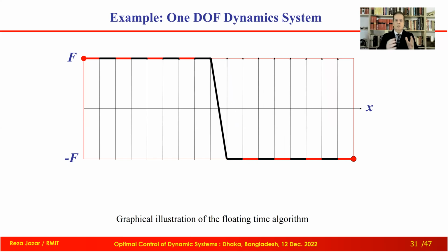Done. I don't know, maybe 20 sections. A very limited section just to show the idea. Now, if you increase the number of these increments, the solution is showing one jump exactly in the middle. This is what we expected from the solution. Now, if we have friction, the equations would be different, but the method stays the same, and the jump or switching point is going to be found somewhere on the right-hand side of the middle point.